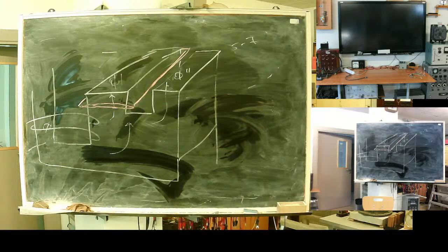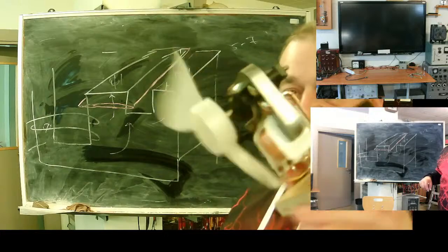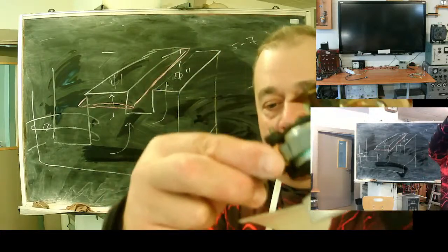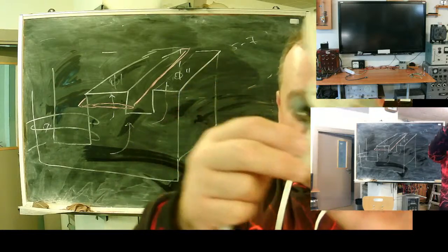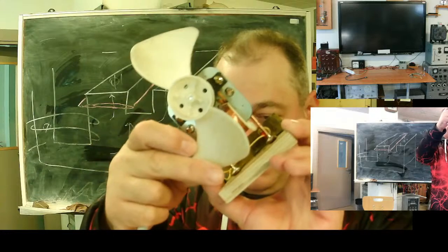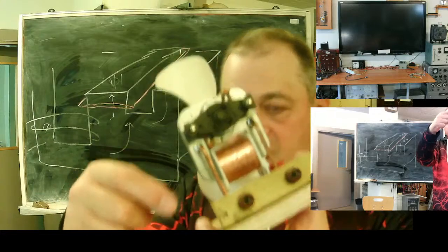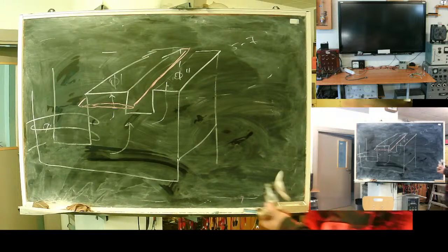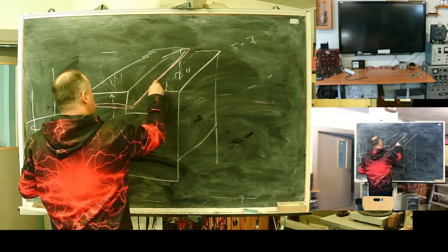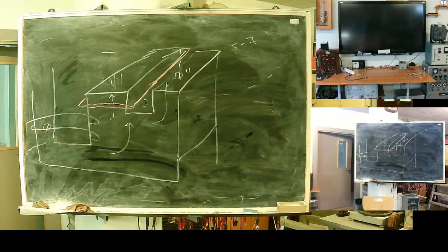Something similar we can find in small asynchronous motors. Here it is screened. Here is a conductive ring covering part of the pole. It shadows or screens part of the magnetic flux, because current will circulate in the ring, and this current will produce its own magnetic flux.